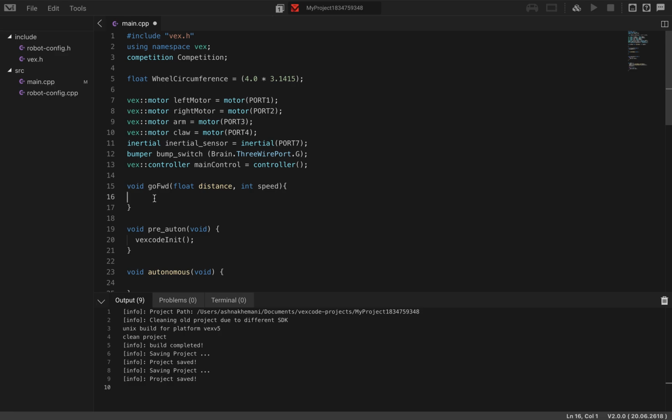Okay, great. Now we need to translate this information into how many total degrees that each wheel needs to turn. And note that I'm saying degrees, not revolutions, because using degrees would mean a lot more precision with the measurements. If I tell you to go 3/4 of a revolution versus 270 degrees, I would assume that you would find 270 degrees a little bit more precise. You can even tune it to 271 degrees or 269.999. So that's why we're going to use degrees.